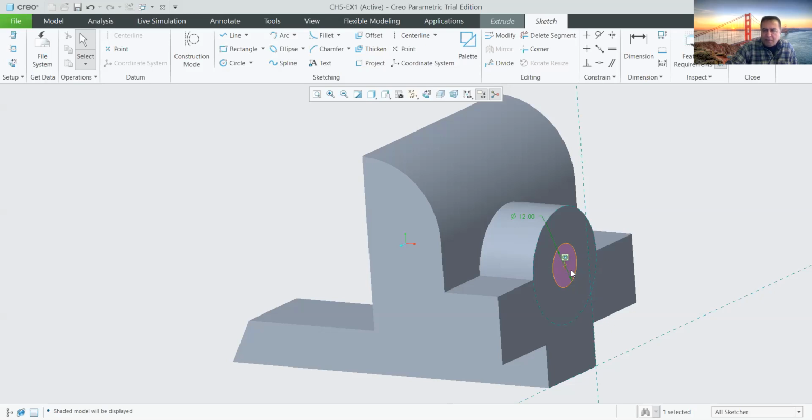The symbol looks like a horizontal line and a little arrow down. That's ANSI dimensioning. The American National Standards Institute dictates the symbols that we use in mechanical drawing, such as tolerancing symbols, dimensioning symbols, and general notes, so that the people in the machine shop can read it, because that's a language in the United States. So we use that to communicate with the machine shop people, so they will not make any errors or mistakes when creating this product.